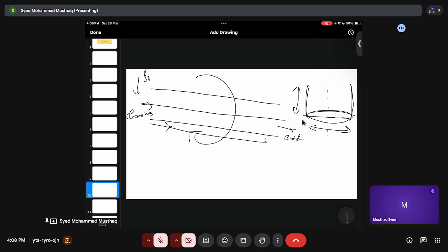Because it is continuously rotating, there will be creation of lots and lots of dust, because there is always this friction between the particles when they are trying to move, and there will be erosion. So that dust will be collected from here, and you have your cooler, and then you do the magnetic separation, because you get mostly metallic iron, which is ferromagnetic and can be easily separated.